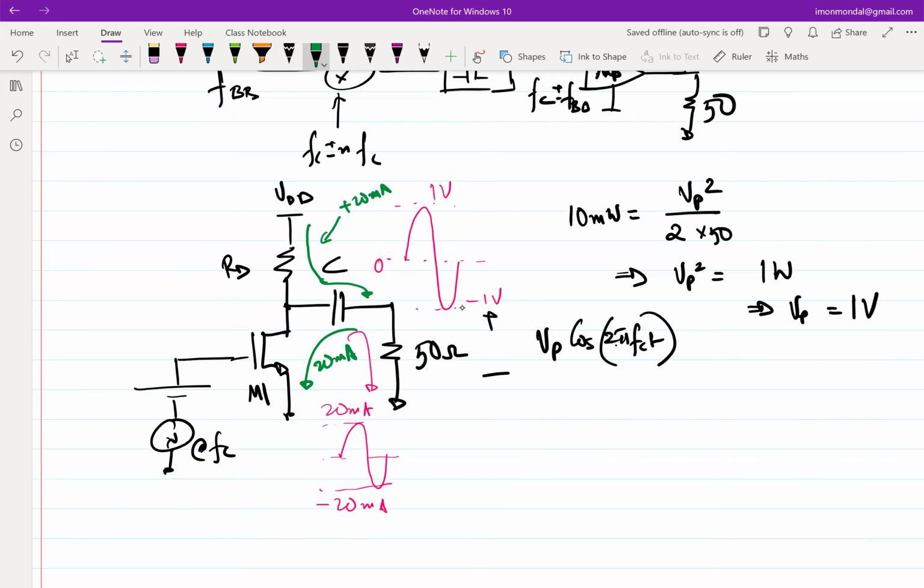That's not a generic statement. The transistor can still be on. Let's say the transistor is right now biased only, no input is connected, right? It's only DC biased. Under this condition, what is the minimum amount of current that you would want the transistor to have so that both these conditions, that is plus 20 milliamp and minus 20 milliamp at the load, are met?